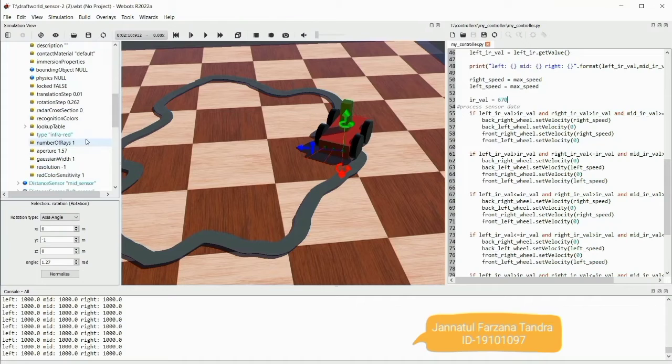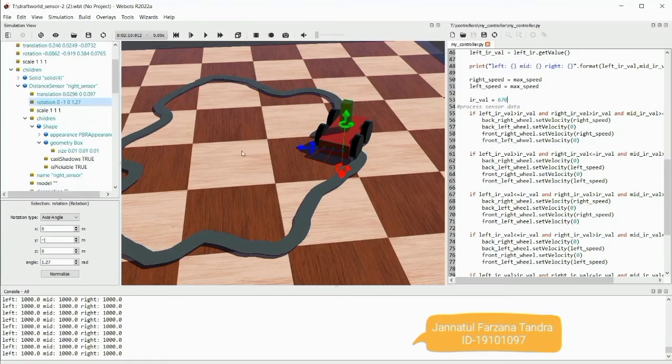As the infrared has an emitter and a detector option, the robot will detect the reflected light coming from the object. So that's how it will differentiate the floor from the line, and then it will detect the line according to the reflected light from the object. And if the light comes from the left side, then it will turn left, and if it comes from the right side, then it will turn right. And that's how the sensor is going to work.